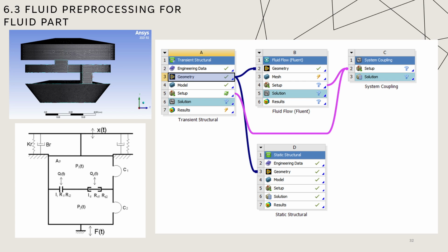So for the two different working conditions, I'm thinking of designing two different models. In the low frequency condition, the inertia track is going to work and it's going to neglect the decoupler, and that is the reason why I will cover the decoupler part, so just let the fluid go through the inertia track.